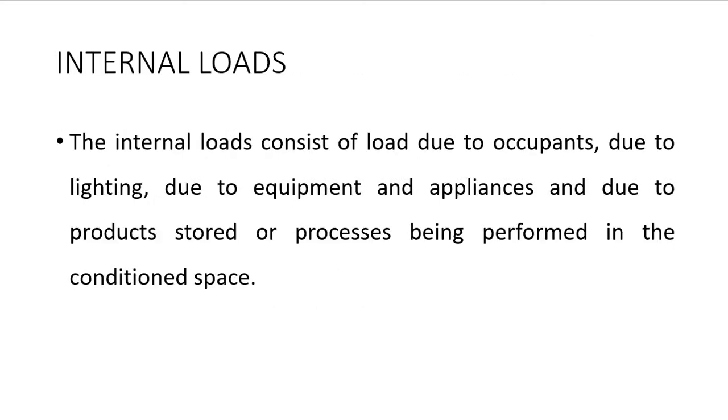Next, the internal load. Internal load consists of load due to occupants, load due to lighting, due to equipment and appliances, and due to product stored or process being performed in the conditioned space.